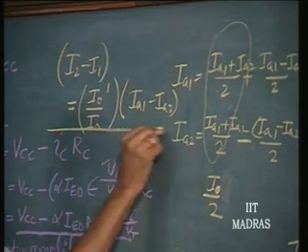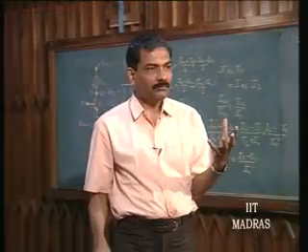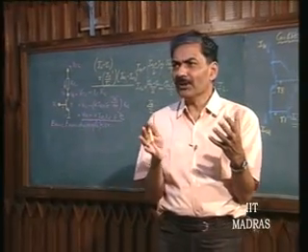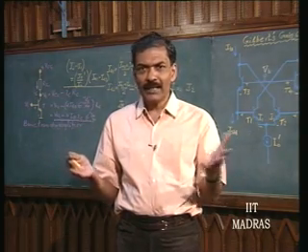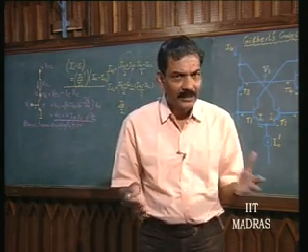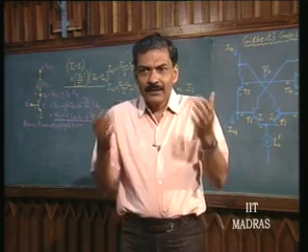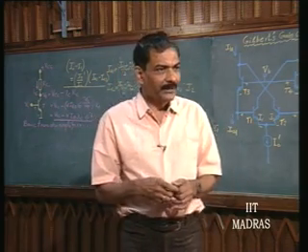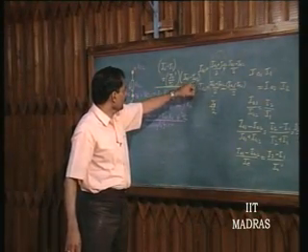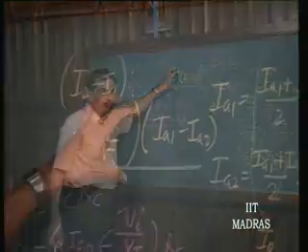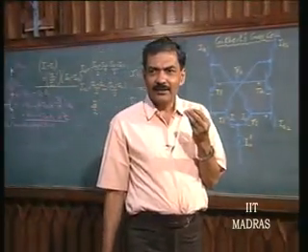So, this is an important relationship in what is called as current mode amplifier. So far you have been exposed to voltage mode amplifiers. Why can't we think of amplifiers as current mode amplifiers? And that seems to be more basic, and that kind of amplification can be done easily compared to voltage mode amplification. Look at the way you have obtained it. Differential input current times a gain factor is equal to output current.